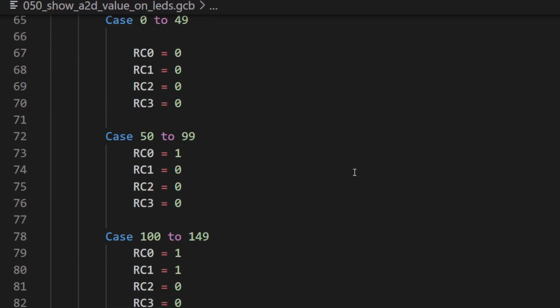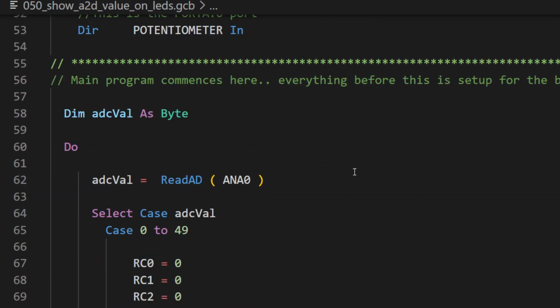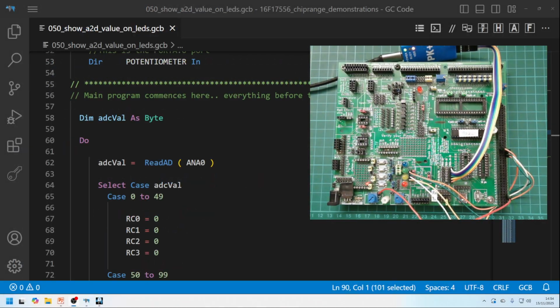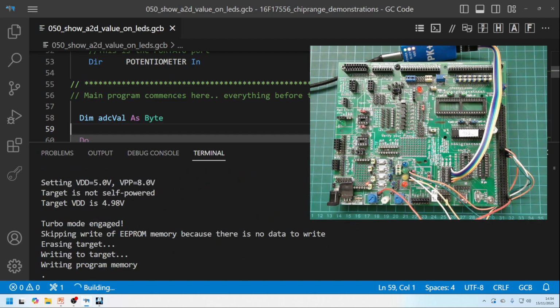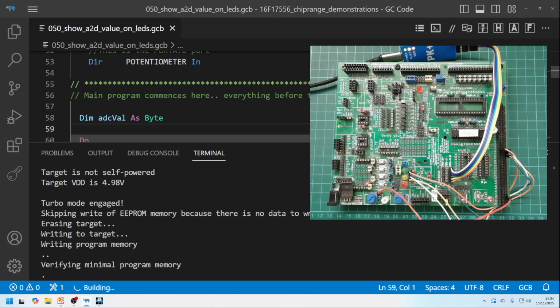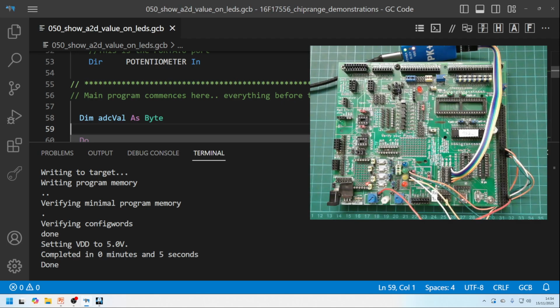To be honest, that's pretty simple to do. So what we can do is program this into our microcontroller, shall we? Let's go out to the camera as well. There we go, there's the camera. And I'm going to press function key F5. I could take this little icon at the top, which says make hex and flash, or I can take the menu from function key F4. But I'm going to press F5. It's compiling it up, taking the parameters that are required from the static libraries, and it's programmed it.